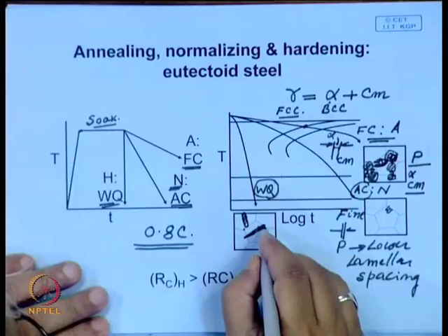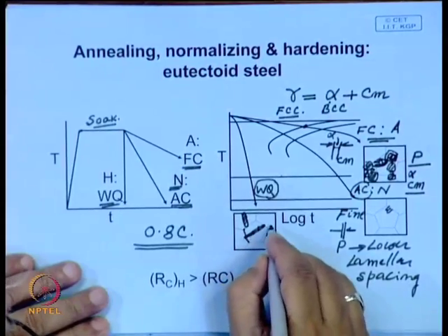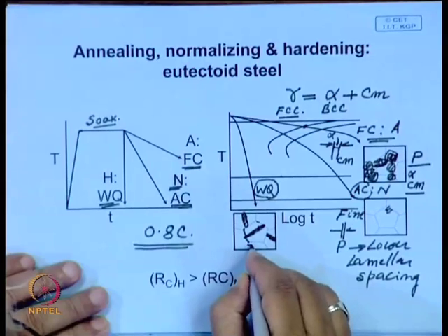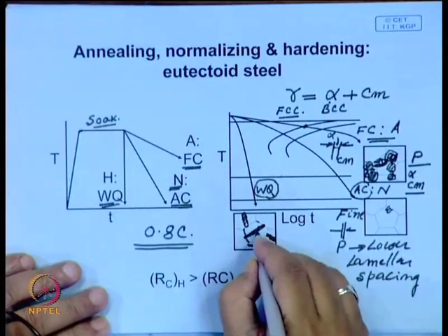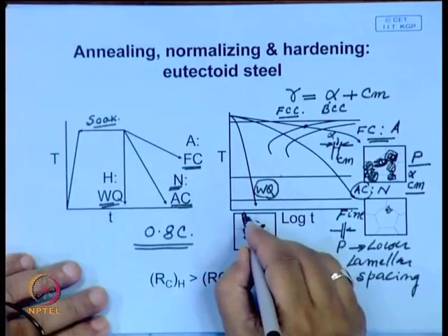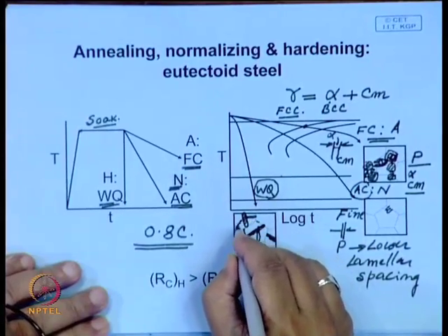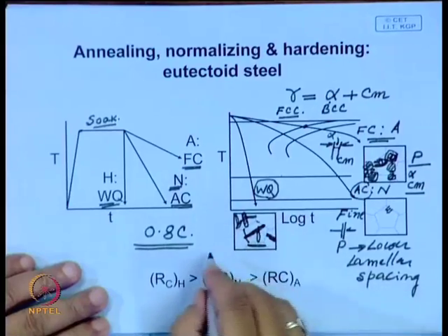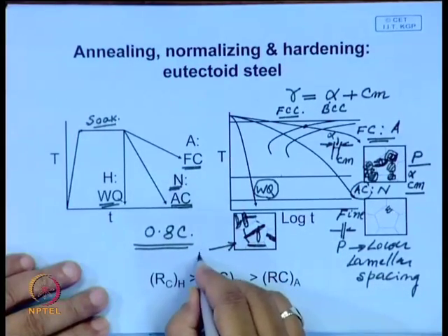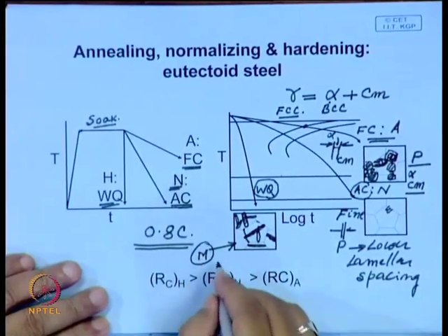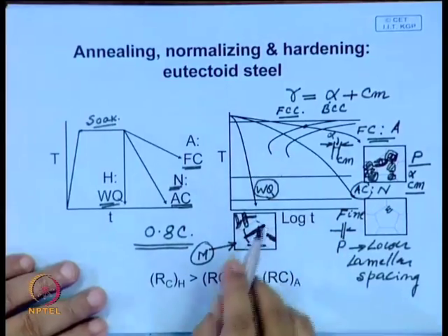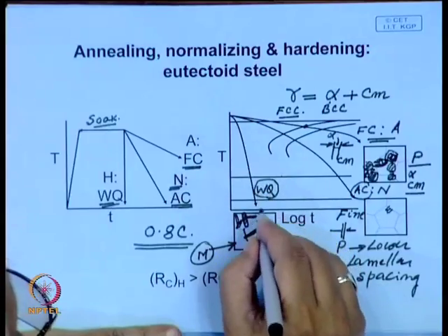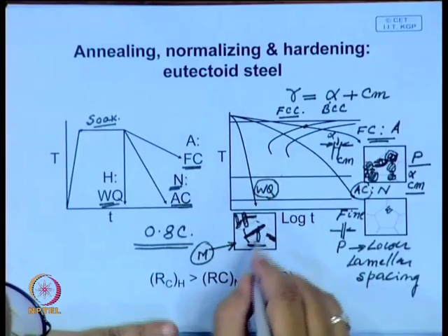When these plates grow, they cannot cross the grain boundary. If it starts from here, it will end on the boundary, and later, when new needles form, they form like this. So, the structure will be made up of martensite, and this martensite process is a diffusionless process, and it takes place through a shear mechanism.